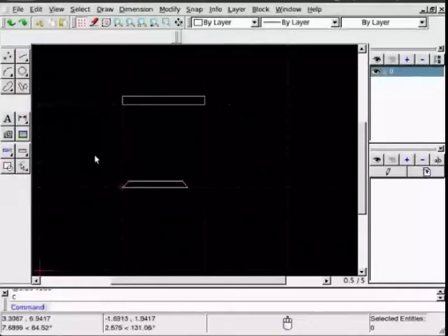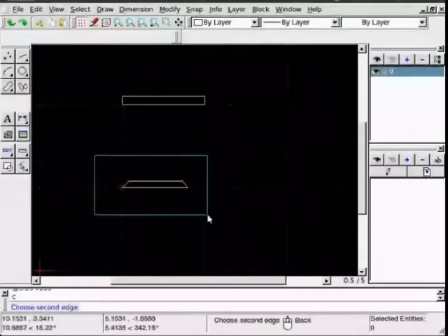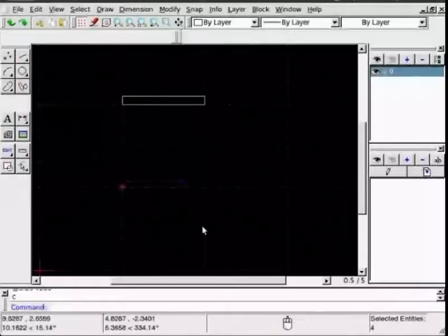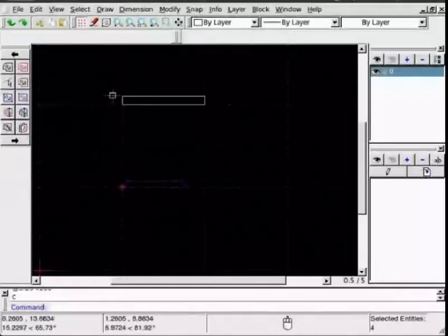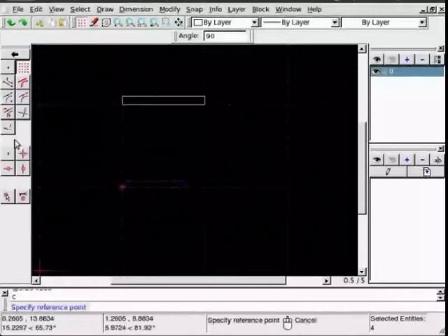So what I'll do is I'll left click once, extend, hold left button and select entire area. And now I'll use modify, move and rotate. Selection is done, so click on this arrow. From snapping option, I'll use intersection.